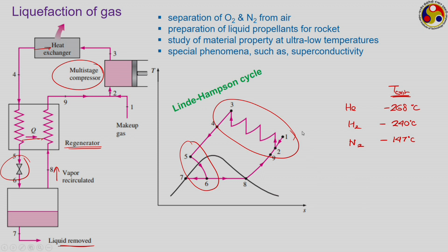So, these are all different varieties of vapor compression based cycle, where we are working with a vapor, and the one that is getting compressed is generally a superheated vapor, but during some stages of the cycle we are having phase change going on, liquid to vapor conversion and also vapor to liquid conversion. But it is also possible that we may perform the entire cycle above the critical point of the working medium, thereby maintaining the gas phase throughout, and therefore we can also have the gas refrigeration system. I would like to talk very quickly about this.